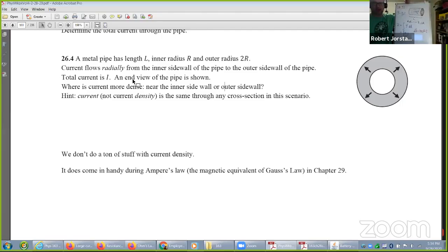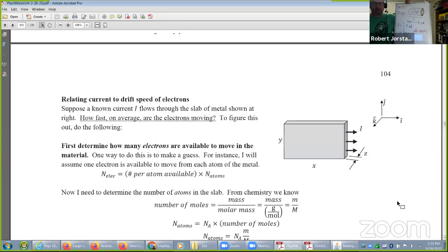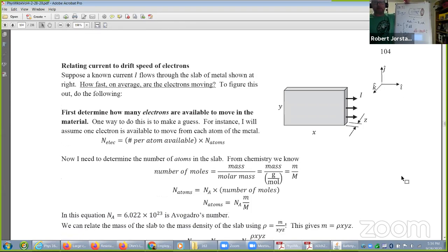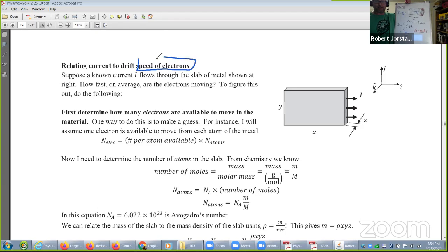Okay. I'm going to keep moving at a good pace, so stop me at any time if I race ahead too far. Now, a common thing that people think, they confuse current with electron speed. As Ryan was saying, normally we have electrons moving in a wire. I just want to point out that the speed of electrons is not the same thing as current flow. They are actually extremely different. Also, notice this keyword, drift speed.